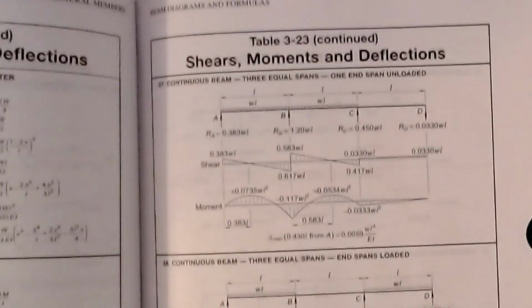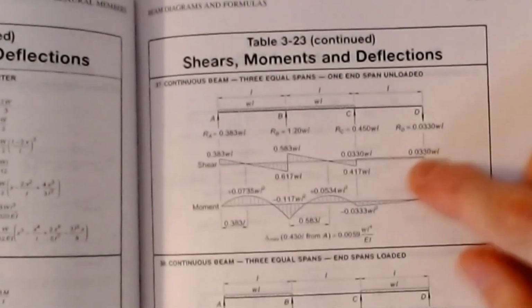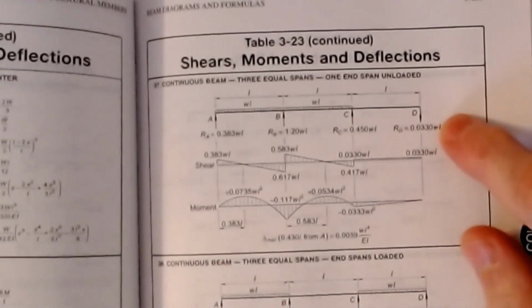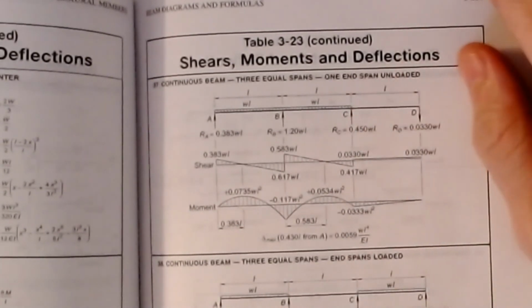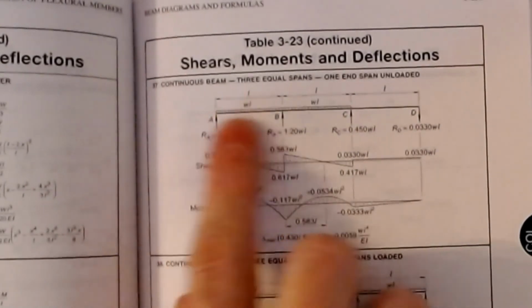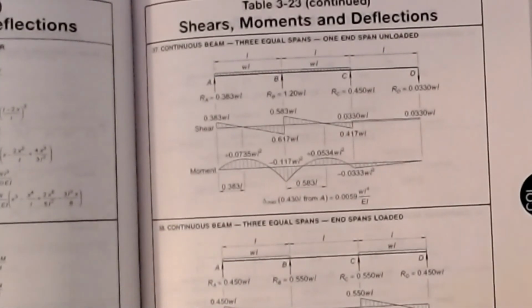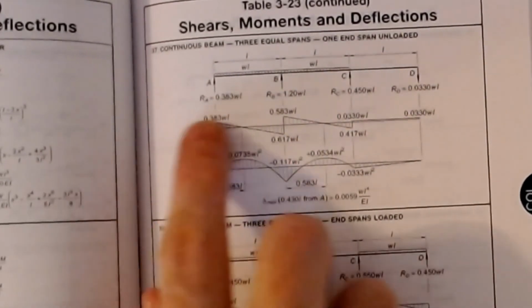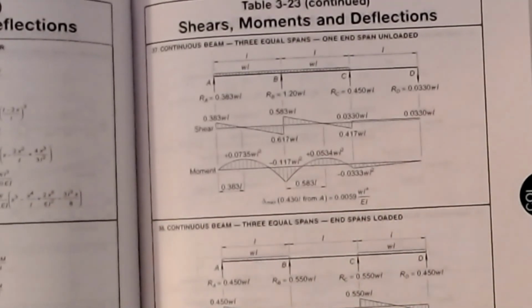They even go so far in these design aids to give you shear and moment diagrams for things like continuous beams. Okay, this is pretty handy because this is a statically indeterminate structure, but engineers face this enough that, based off of my load patterns, for a case where I load 2 bays and 1 off, here are my diagrams for the shear and moment, and then it's just a function of the load and the spans to come up with these coefficients. It's super, super easy, and I don't have to do all the structural analysis stuff that we've been learning in these last couple of lessons.